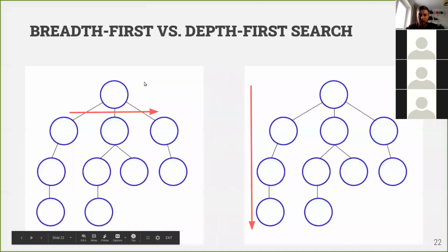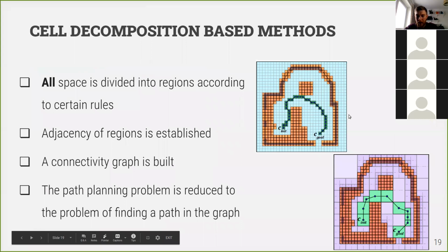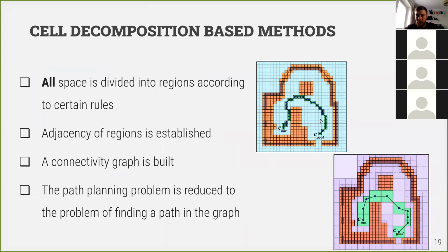So usually Euclidean distance, or L2 norm, is used as this heuristic. What does it mean? Imagine we have this map, we have it in advance. And for example, we know that we want to move to this goal configuration or goal cell. So in advance, for each cell, we can find the Euclidean distance to this cell, right? Just by measuring straight lines.